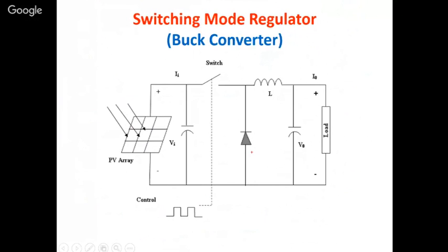With this itself, if you want to make this a boost converter, what you do is, in the anti-clockwise direction, just shift these devices. I used to tell my students to remember this, because whenever we ask about buck or boost converters, they get confused. Only this inductor will come here, the switch will be here, and this diode in the forward direction like this.